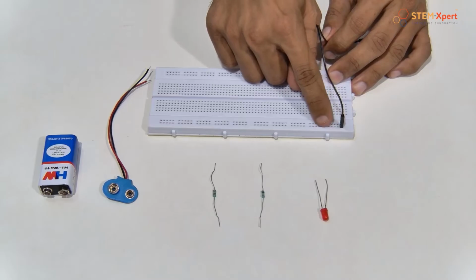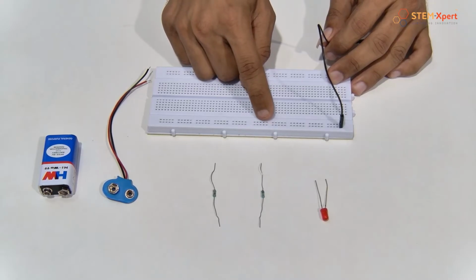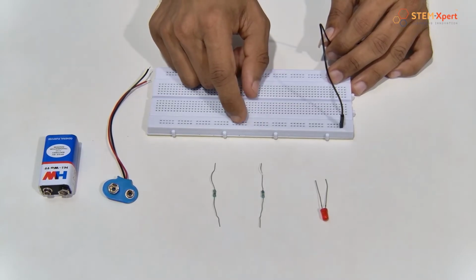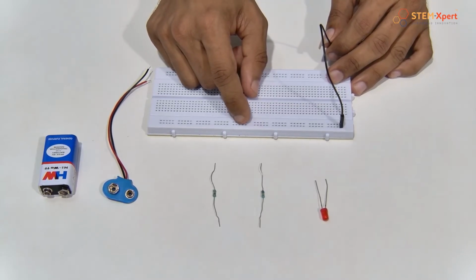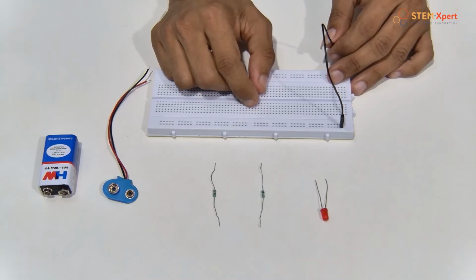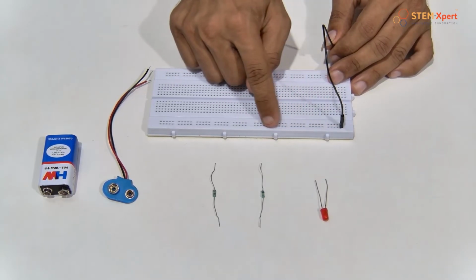Then I can get the positive voltage from this entire row only up to 5 sections. Am I right? Yes, because after the 5th section of this A part, it is not interconnected with the next one, that is the 6th one. So if we want to get that positive from other points after the 5th section, we need to connect it along with the first 5 sections of the A part of the breadboard. So simply, in the A part and D part of our breadboard, connections go horizontally.